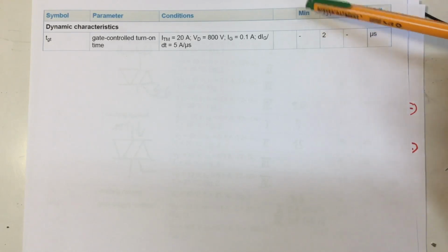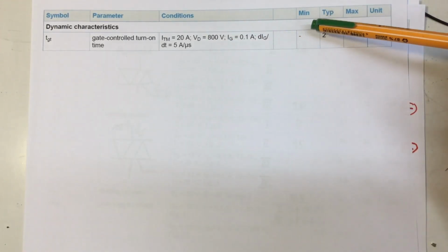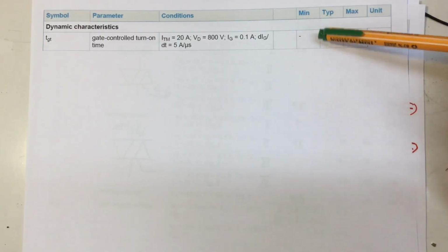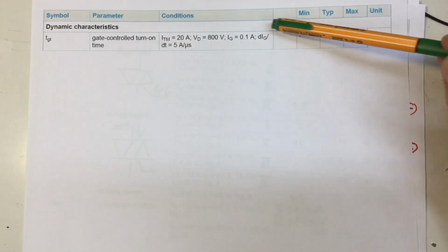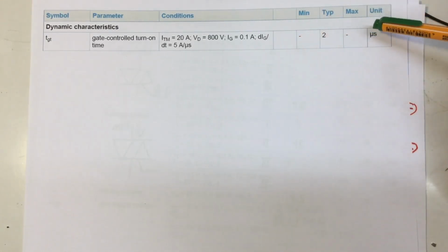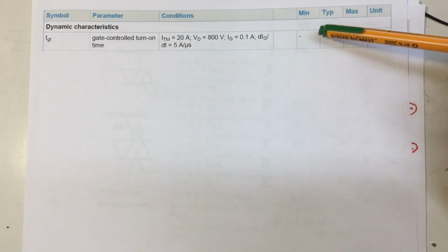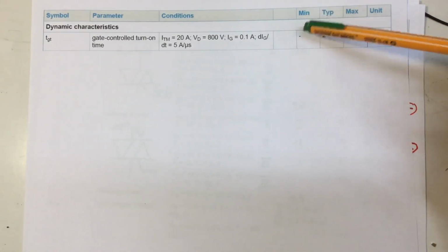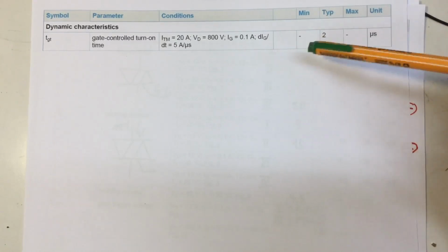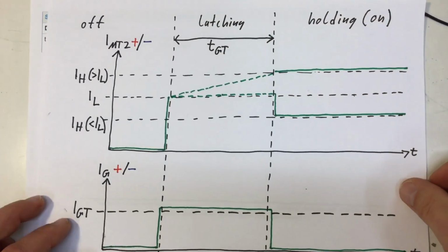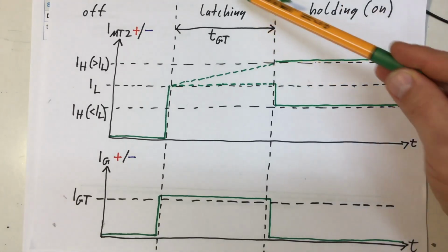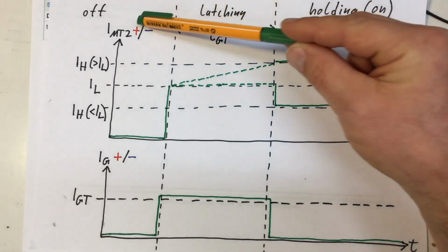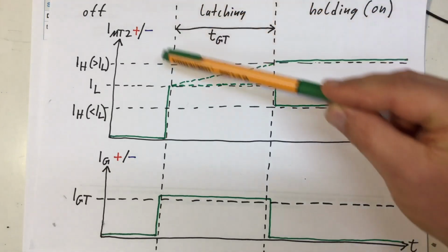It fires how we're driving it at 1 microsecond pulse duration perfectly. And when you then go down below 0.5 microseconds, it really starts to struggle. And below 0.4, it cannot latch on anymore. And that's exactly our last parameter that characterizes the gating, latching, and holding of the whole thing.